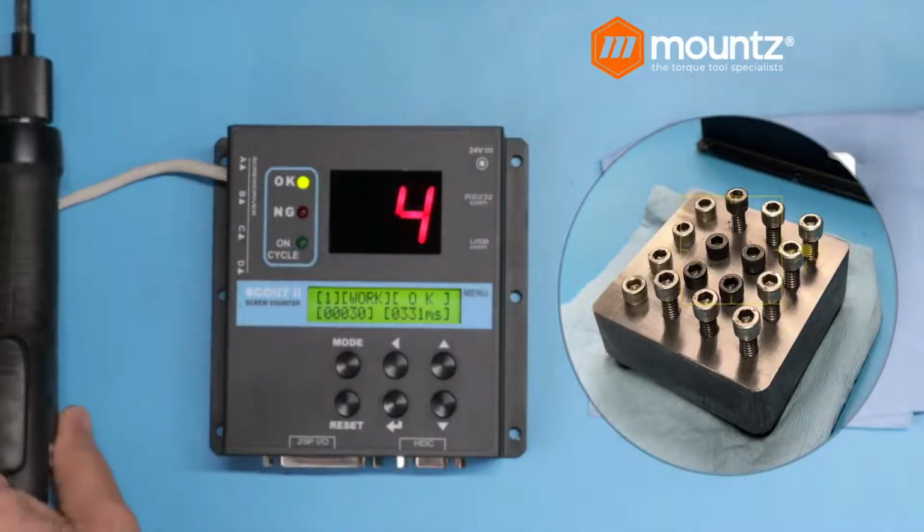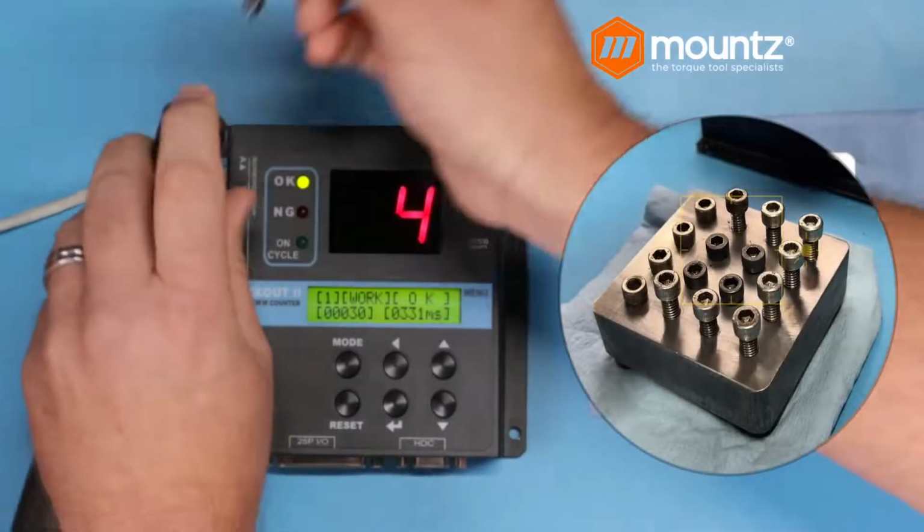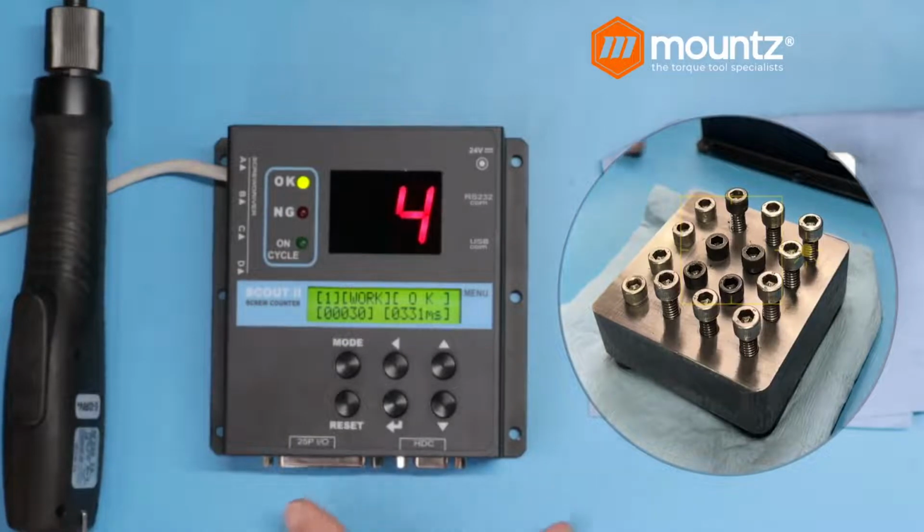Now this particular system can be controlled and used with the I/O information that we have available. So if you have a particular input device that you need to control which program you would like to use, 1 through 8, that will allow us to use those types of input signals to call out a specific profile that needs to be used, or it can be done through the PLC selection as well.